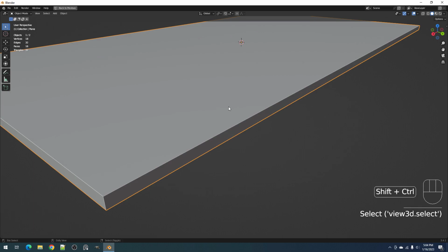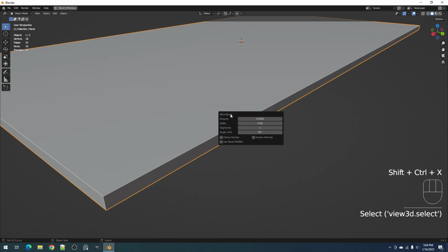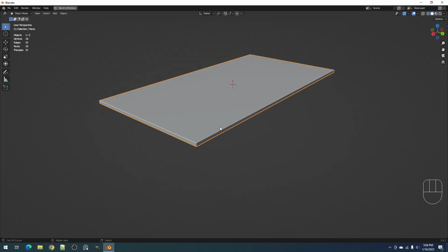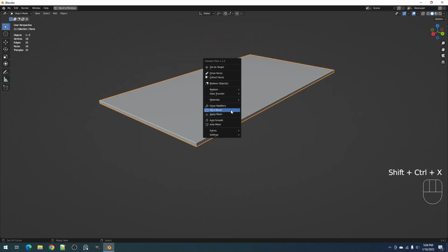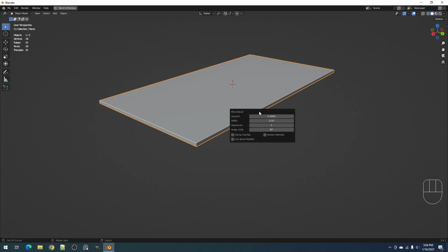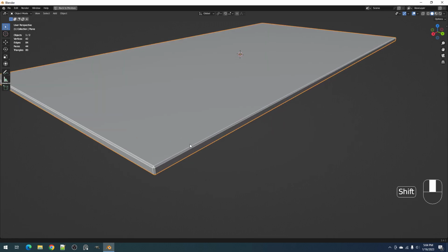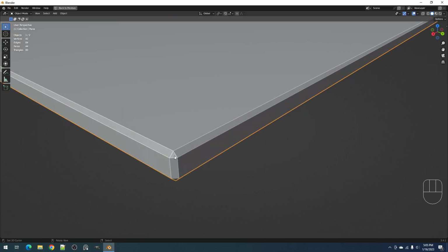And then we need to add a bevel modifier to this, or an edge split. Yeah, let's start with the bevel first before the cuts. Okay, so that's solidify modifier, and then we have the bevel modifier using the micro bevel operator. So use bevel modifier and adjust the amount or the offset or the width of the bevel.